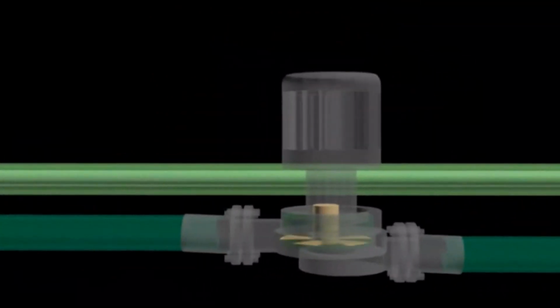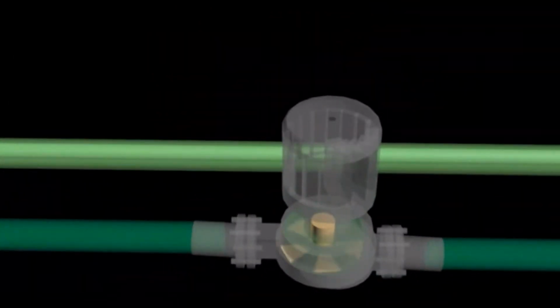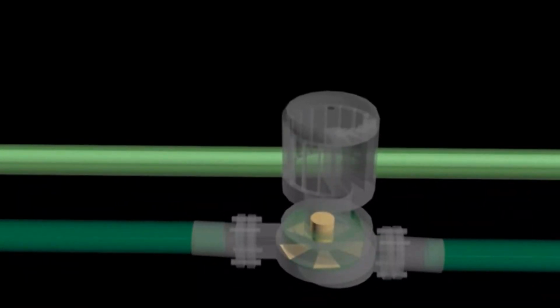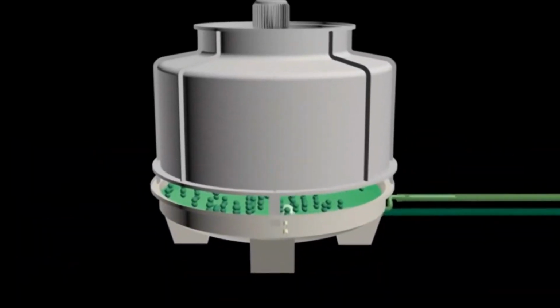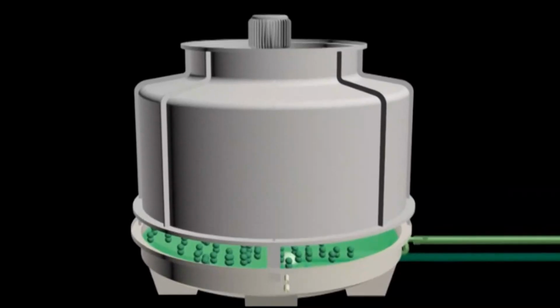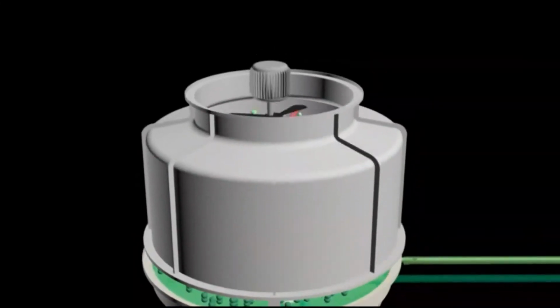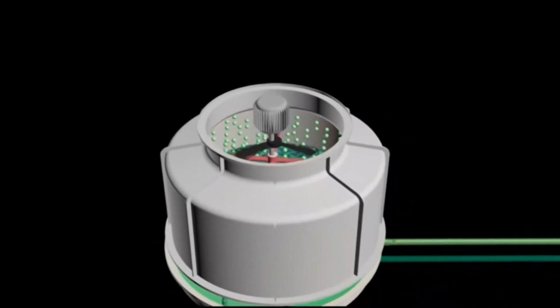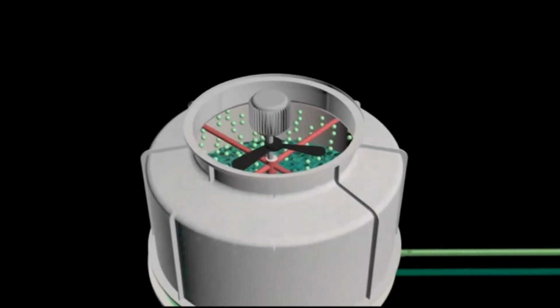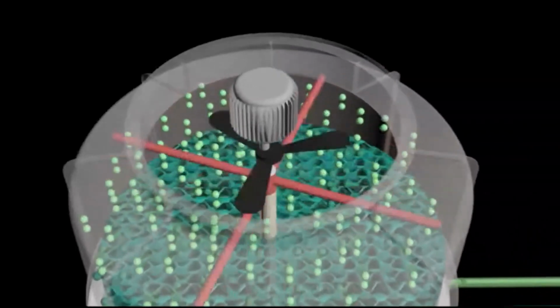From the condenser in the chiller, condenser water flows to the cooling tower with the help of a centrifugal pump. This water is called condenser water return. This condenser water will pass through the rotating sprinkler blades on the cooling tower. These blades rotate using pressure generated by the condenser water itself.